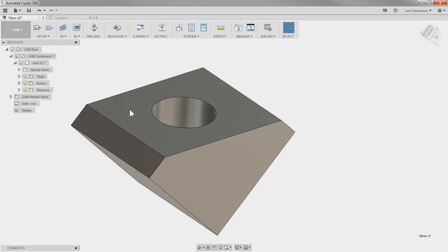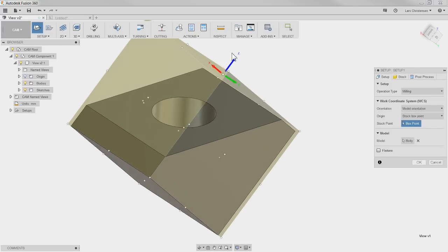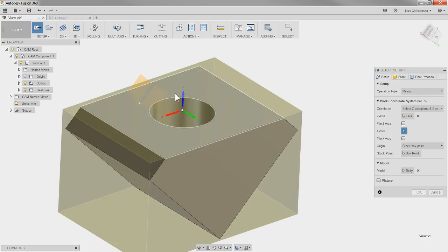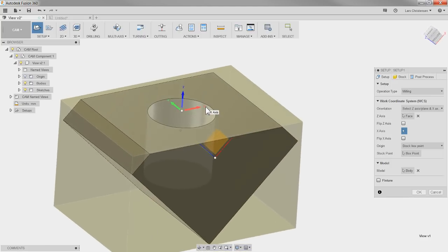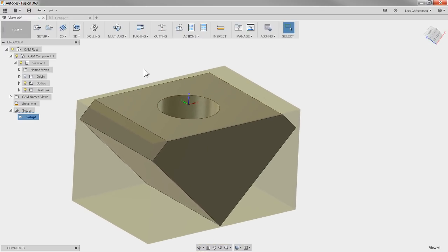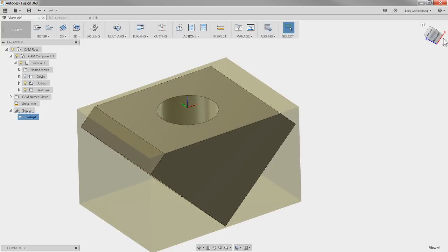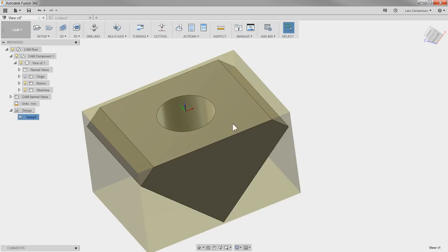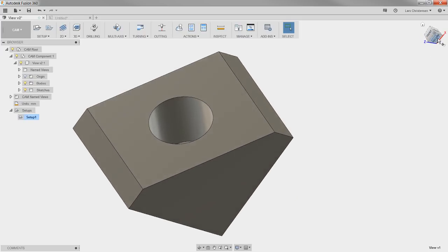But in here, if we were going to machine this flat surface and this hole, we will go in and create our own setup, because in CAM we don't really care too much about the view up here. We can create our own kind of datum like this. But CAM guys sometimes email me and say, it really bothers me that this view cube is way out of whack. When I'm in a view like this and you've got Z up and this is where I'm working, why can't I get this view cube to resemble that?